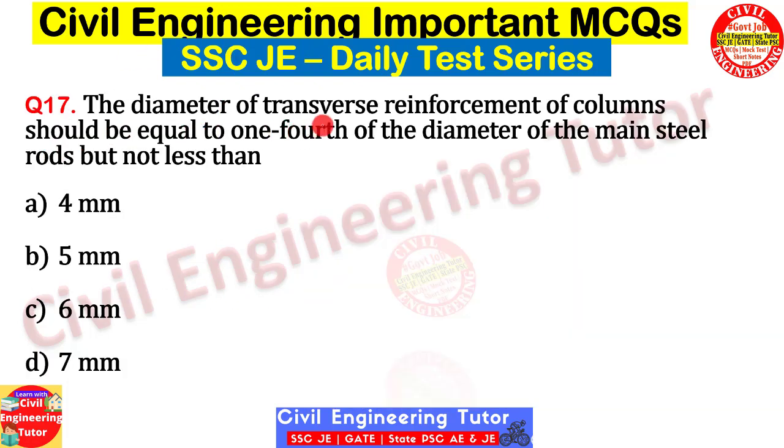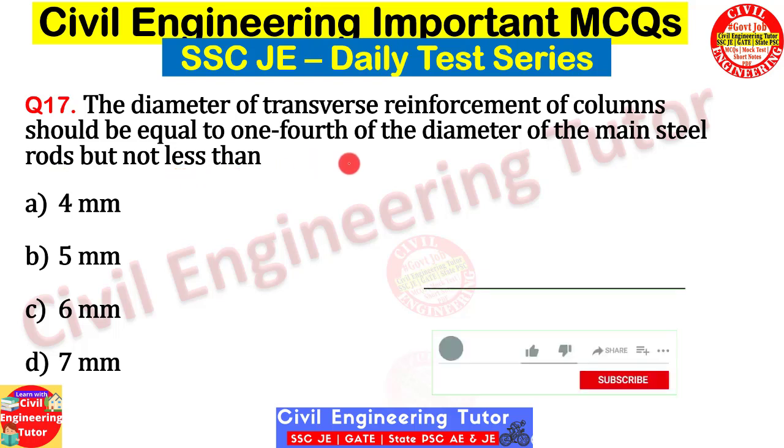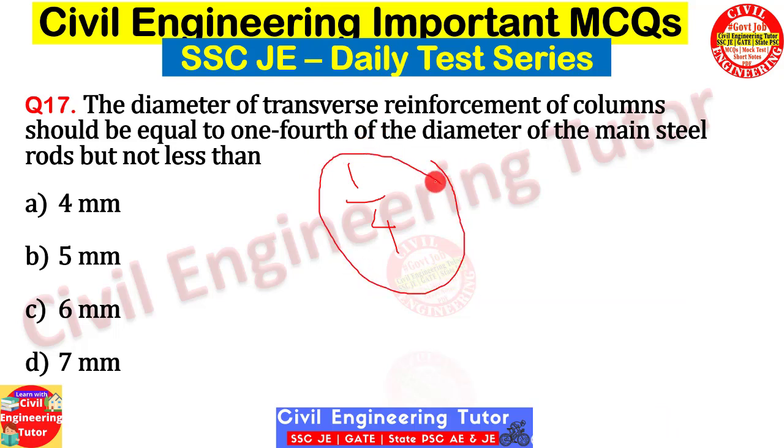Next, the diameter of transverse reinforcement of columns should be equal to 1/4 of the diameter of the main steel rods, but not less than. So we know this is the codal provision, that the diameter of lateral or transverse reinforcement that we use should be 1/4 of the diameter of the main steel bar, but there is a minimum value. And that minimum value is what? 4 mm, 5 mm, 6 mm, or 7 mm. So you just need to remember this codal provision, and the correct answer will be C, 6 mm.